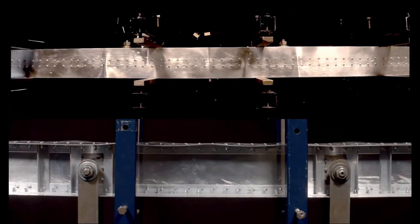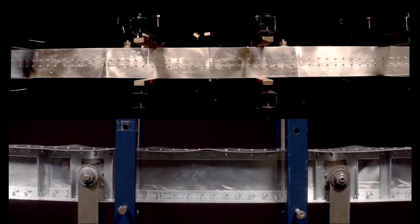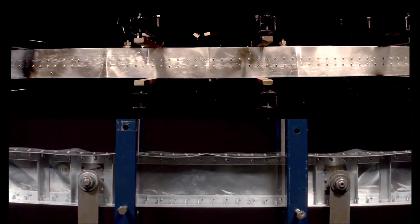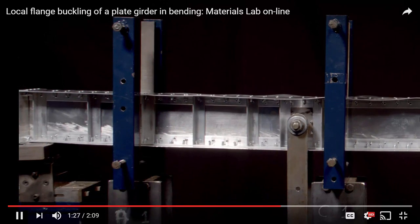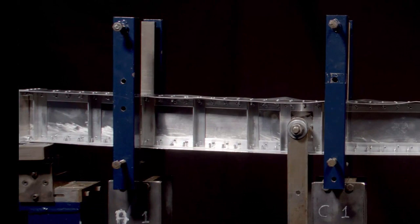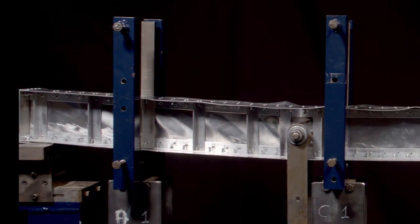Now let's zoom in on the central portion and at the same time look down from above. You can see that the ripples are evenly distributed along the top of the flange. Eventually the flange shows plastic deformation and failure occurs. Let's have a look at the left-hand end of the beam to see another effect. Local buckling in the flange reduces the stiffness of the overall cross-section, which affects the internal stresses within the beam. Here, shear buckling of the web is seen as a direct consequence. This type of combination of buckling modes can in fact cause the beam to collapse catastrophically.